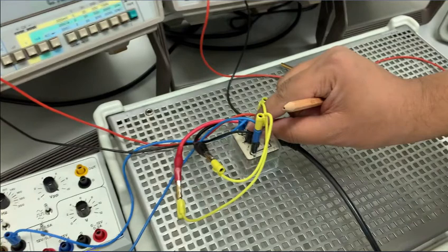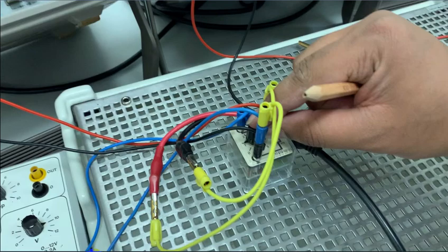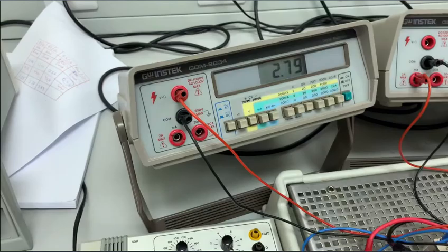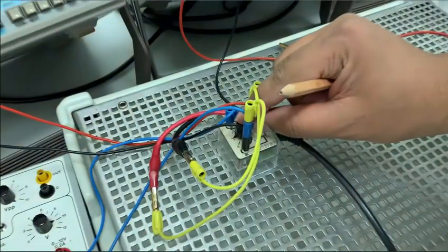Okay, what is the value you are seeing here? It is the RMS value. 2.79 is the RMS value. Here you have peak to peak and RMS value. Peak to peak you will get from the CRO, and the RMS value is 2.79. So if I just take the RMS value, I can directly take 2.79. If I want to take peak to peak, we can convert it to the RMS.